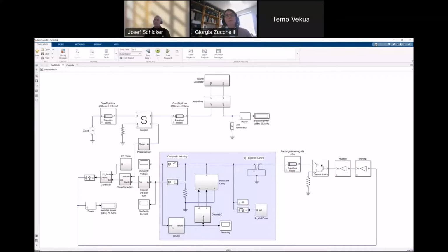When we look at this model overall, you notice, if you have good eyes, two things at the first level. One, that they have two different types of signals. You see we have certain lines that are dark blue, like these ones, and certain lines that are black and marked with a single unidirectional arrow. Here we are really combining two domains of simulation. The signals indicated with a black arrow are essentially Simulink signals.